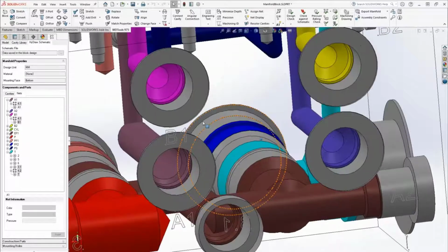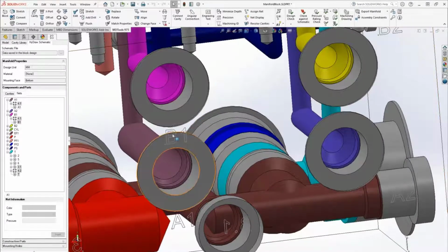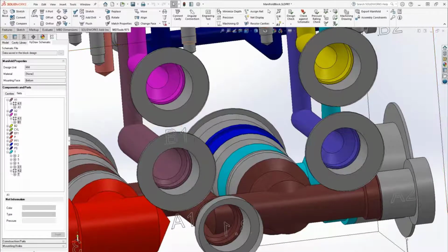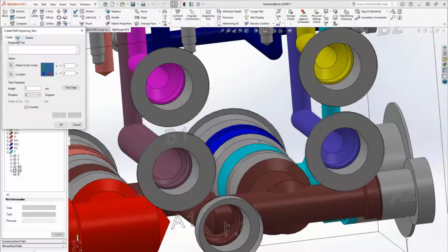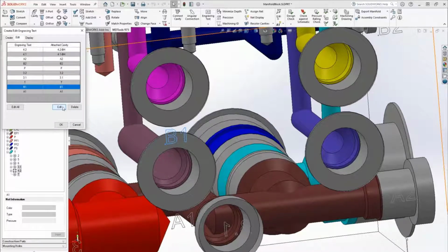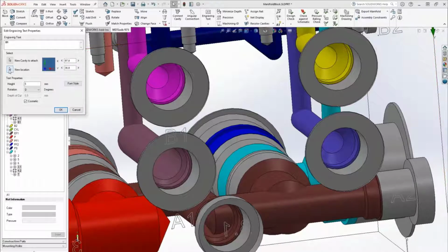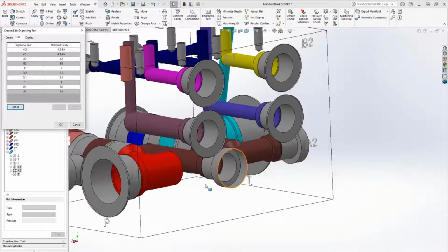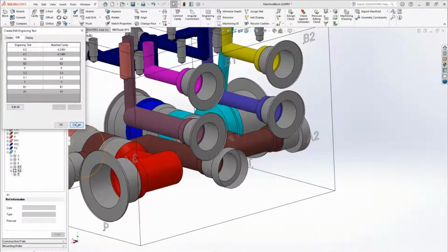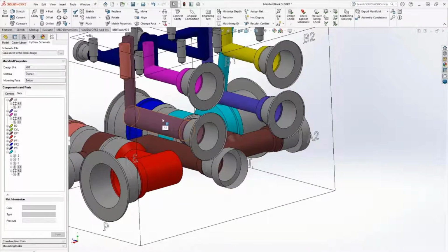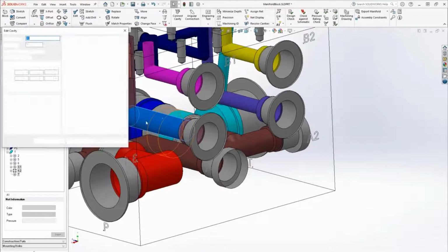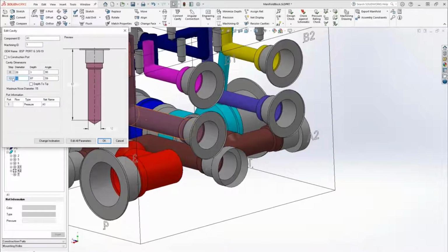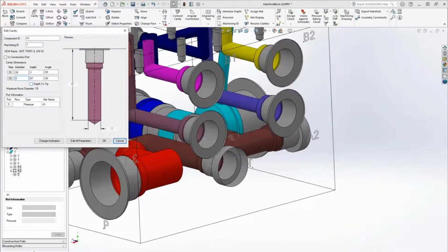By default, the engraving is always put down the cavity. So in this case, we'll need to move the engraving. So B1, edit, and we can change the position. A1 is good there. I forgot to change the diameter. When you need to change the diameter of a cavity, you touch and edit, and you can change the diameter as a step 12. Let's make it 8 millimeter.